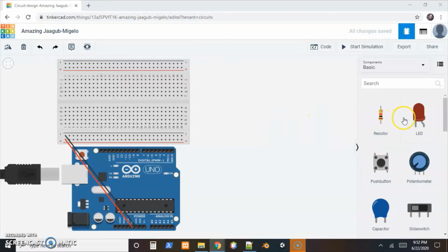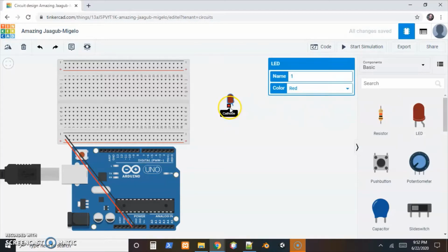So we're just going to do a simple circuit here. Let's start with 1 LED and just make it flash. So we bring it over, and you'll notice in the picture here, one of those leads is longer than the other. If you need the labels, anode is longer than the cathode, and the anode goes towards the positive side, and the cathode goes towards the ground side. Or just remember, the shorter wire goes to ground, longer wire goes to the hot. So just bring that in here and stick it on here somewhere connected to a couple of rails.